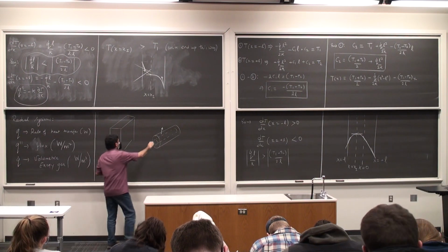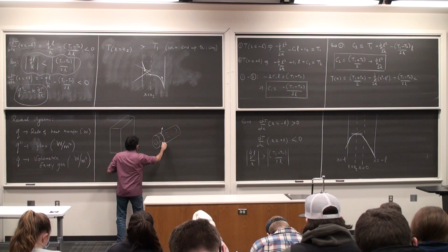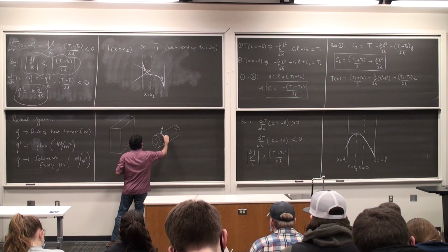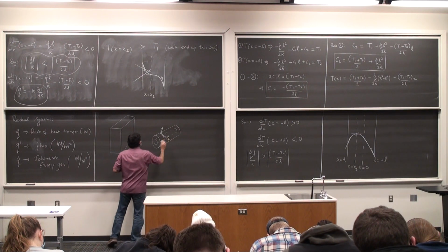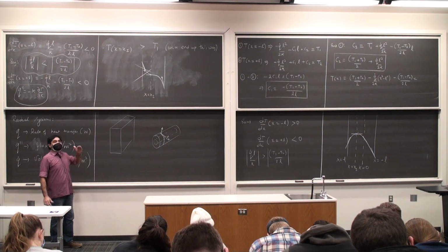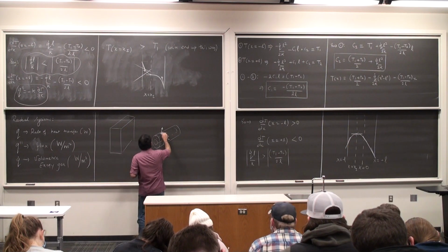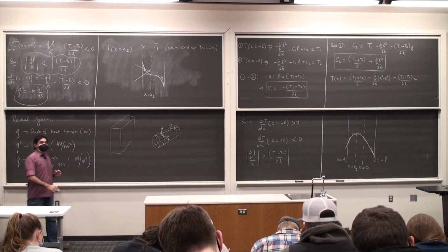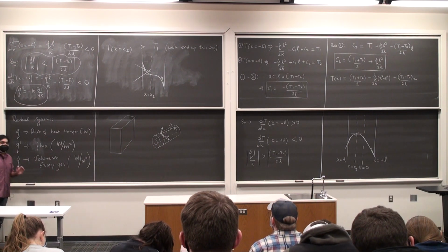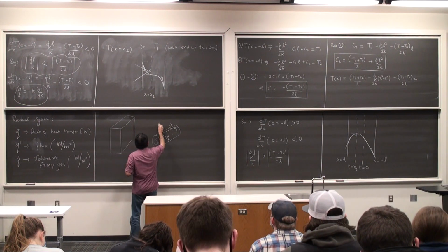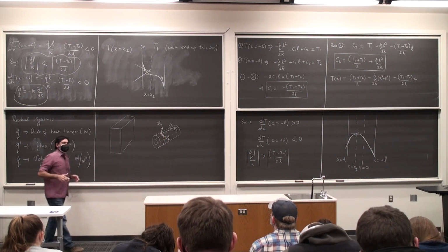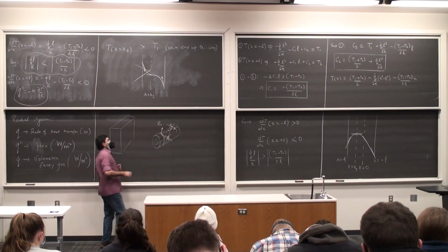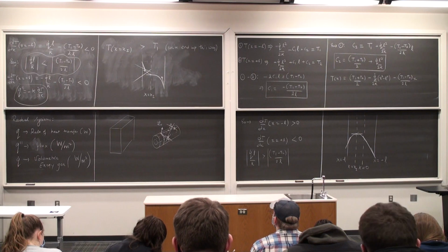If I look at a curved surface, I can draw three unit vectors. I can draw a tangential unit vector, E suffix t. I can draw an axial unit vector, E suffix z. And then I can draw a radial or a normal unit vector, which I call E suffix r. Et is typically called E theta, if you like. We will not be looking at heat transfer in these directions. We will be looking only in the radial direction.